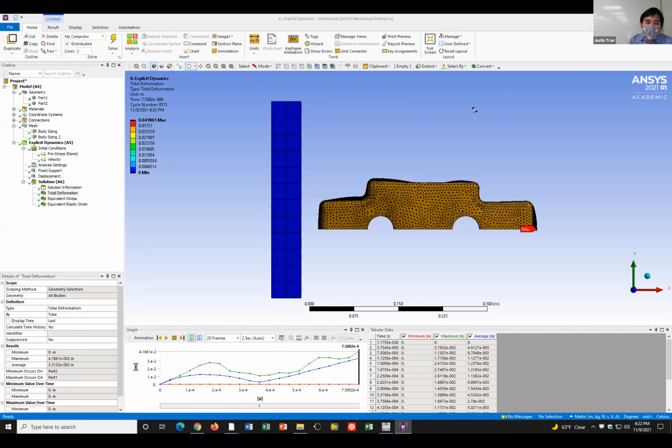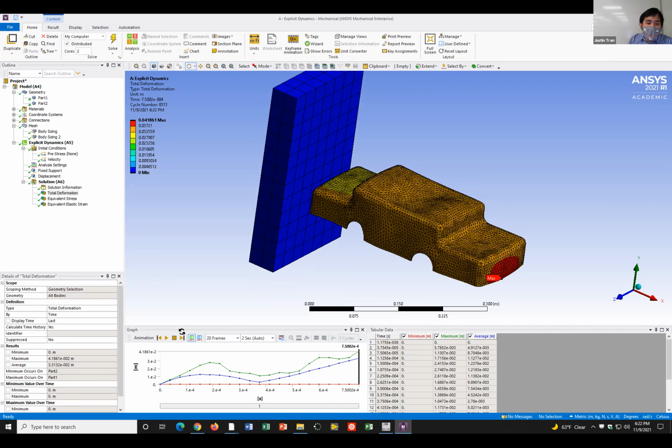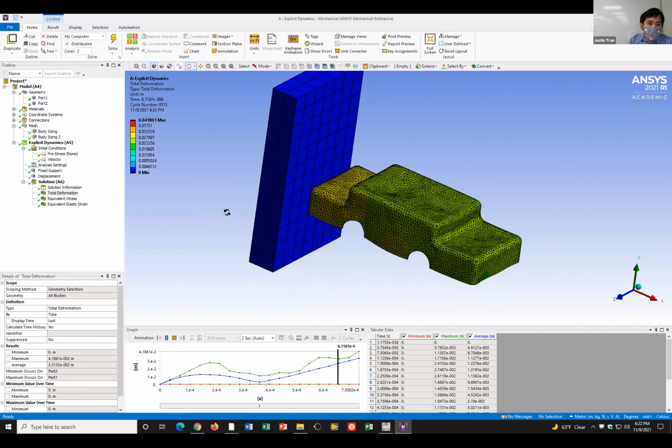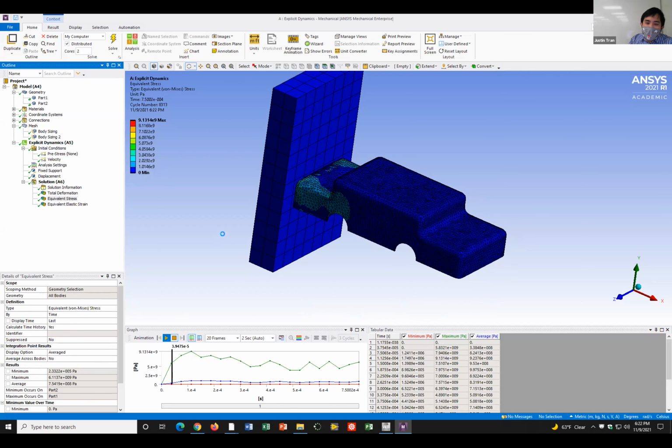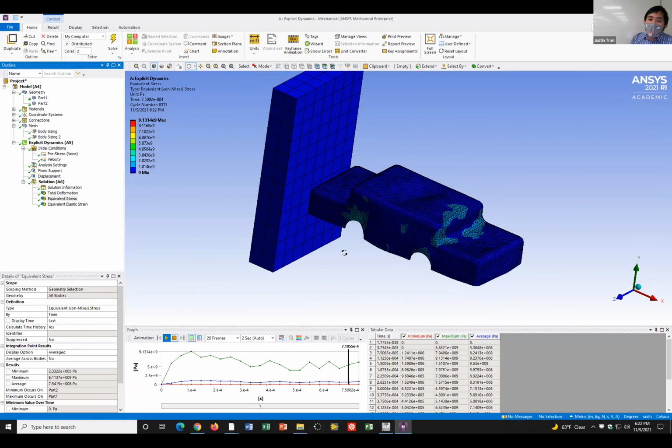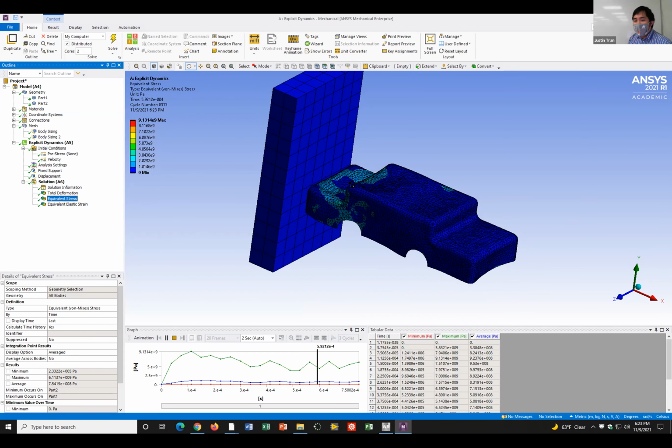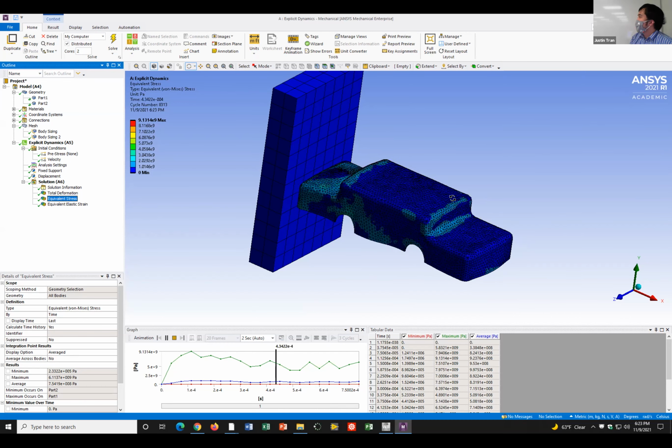Yeah, it looks like the car is made out of jello. So this is what happens when you give an initial velocity of 150 meters per second. The reason I have that in the activity is because I think this is the coolest. It looks a lot cooler than before, but it's also very unrealistic, because 150 meters per second is like the speed of a bullet. If you shoot a car at the speed of a bullet at the wall, the whole thing should just crumple. But you can see it just jiggles and jiggles and jiggles instead.